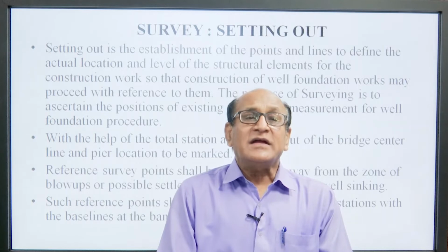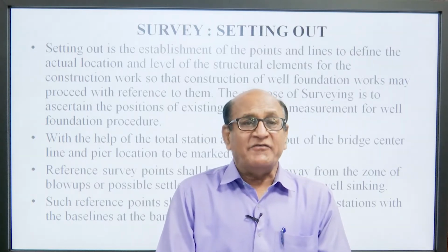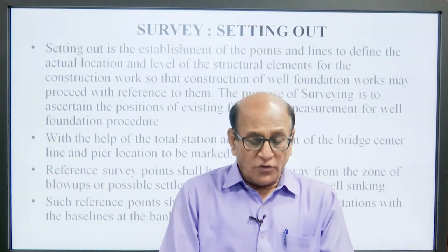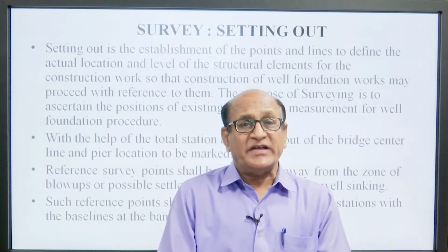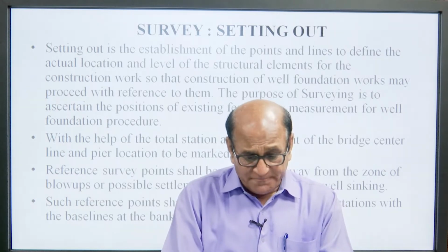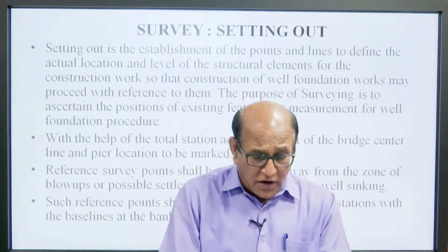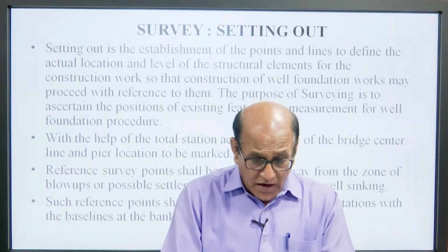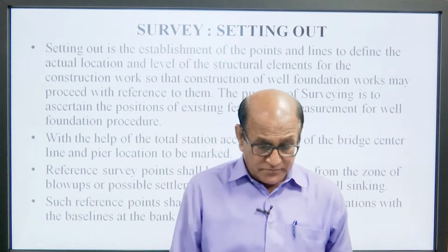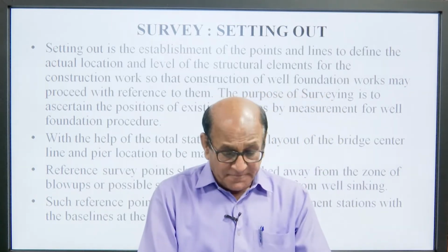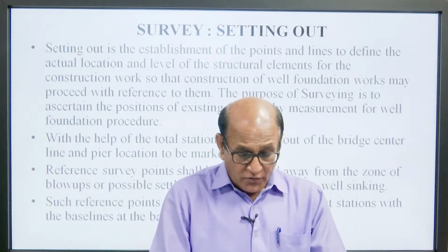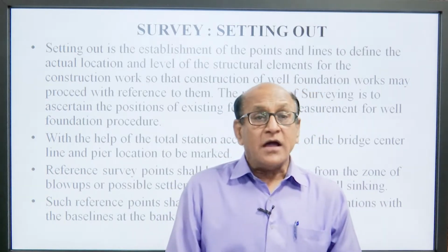So, for work like a bridge which needs to be very precise, we will take up total station for surveying purpose, for setting out the work. A reference survey point shall be established away from the zone of blow up or possible settlement area resulting from well sinking. Such a reference point shall be connected to a permanent station with a baseline at the bank.